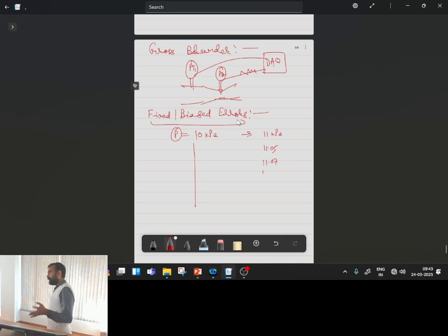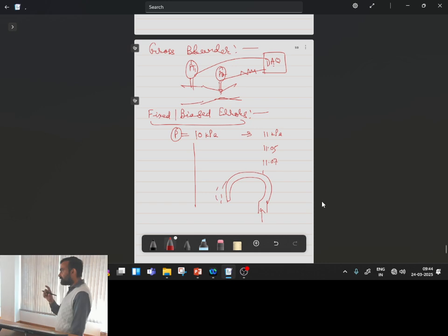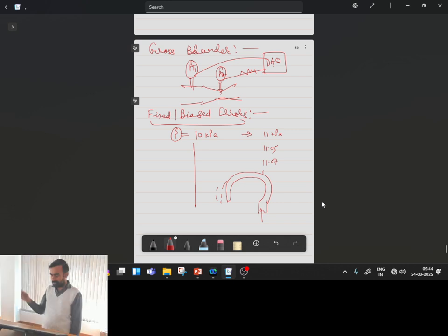Once we have a constant gap, and that error comes every time, it is called a fixed error. Typically why does this error come? It comes because of changes in the measurement device once it is used for a long term. For example, if you use a pressure gauge, we know how a Bourdon tube pressure gauge functions. It has some hollow tube, and from here pressure is supplied. When pressure is supplied, for different pressures the deflection of this tube happens, and this deflection is noted in terms of changes in the reading through some calibration process.